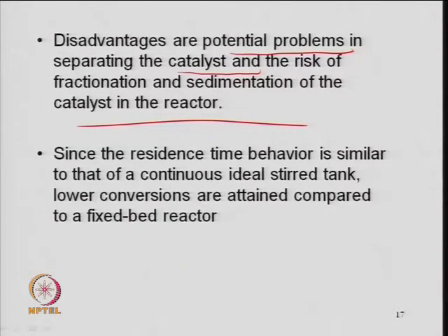Residence time behavior is again like a CSTR, because I told you that all these reactors, bubble column reactor, suspension reactor, slurry bubble column, resemble a stirred tank reactor, right. So, the conversion will be low. If the conversion is low and you want high productivity, you need a larger size of the reactor. So, a large size of the reactor will be required compared to a fixed bed reactor, which works like a plug flow.